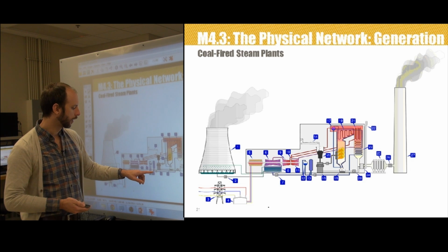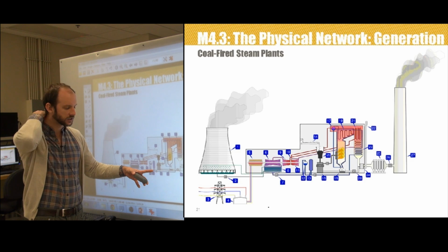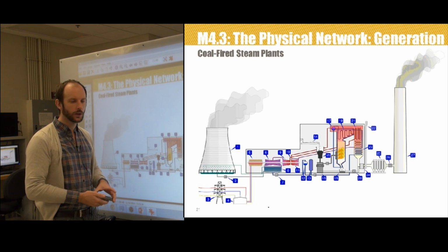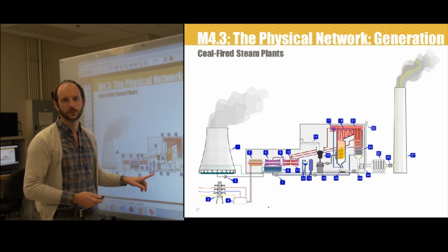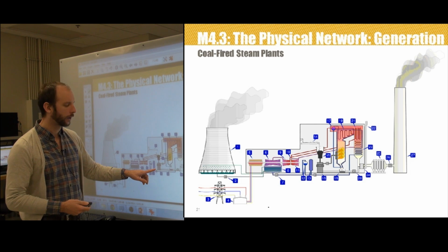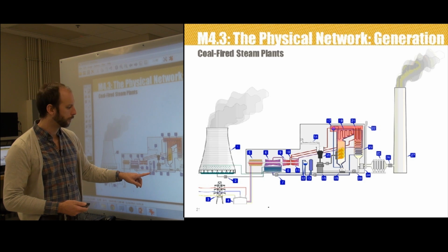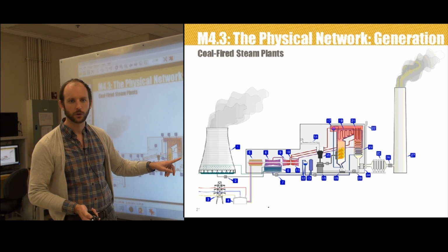After the deaerator, it goes into a feed heater, 13, which just heats that condensed liquid up. It's not high pressure though, it's just warm. So this is a pre-warming stage in 13, which is again the feed heater, and all this is, by the way, powered by steam action. And then it's sent back to the boiler drum here.